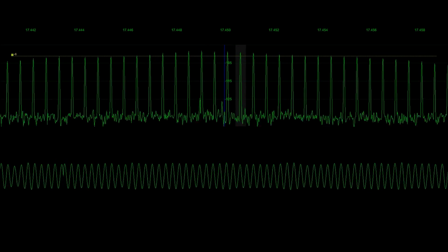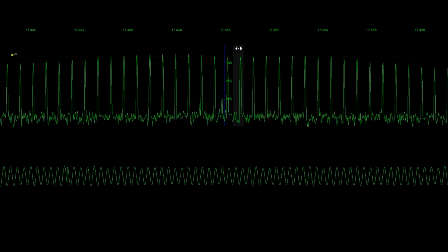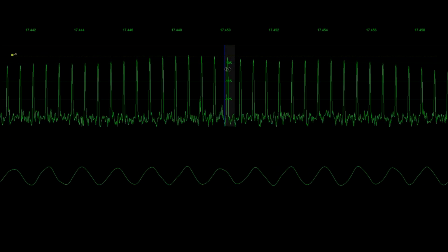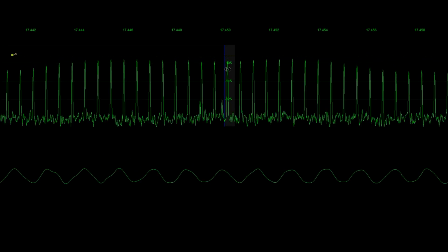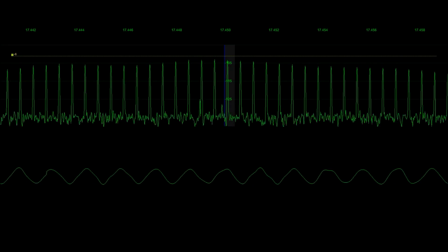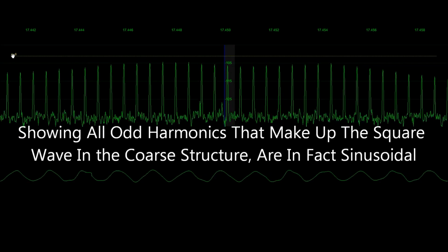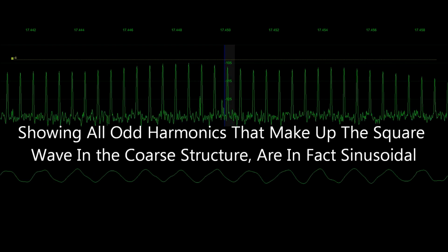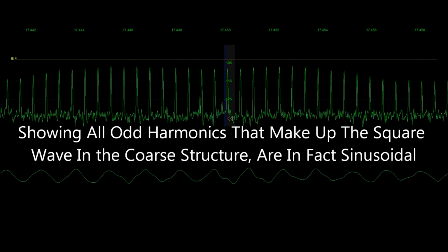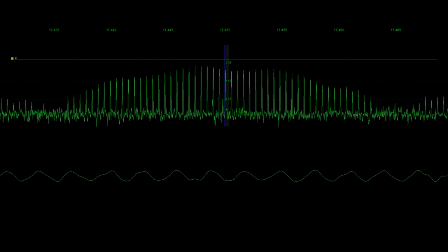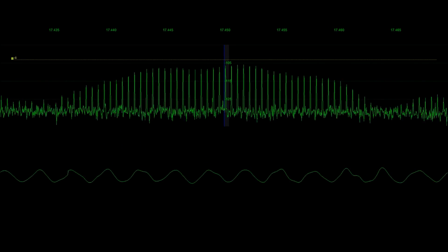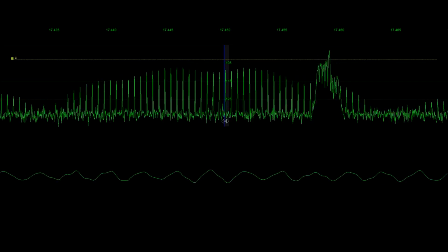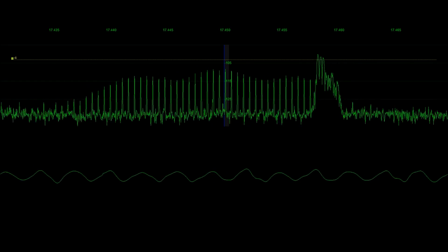Let's zoom in a little bit more and isolate an additional carrier. Okay, this particular carrier is approximately 137 cycles above the center of the receiver. And in this case, again, you can tell quite easily that these are sinusoidal audio waveforms that we're demodulating with the help of the beat frequency oscillator. So this is a really great example of being able to actually start to analyze some of the individual components here of what these modulation techniques really are.